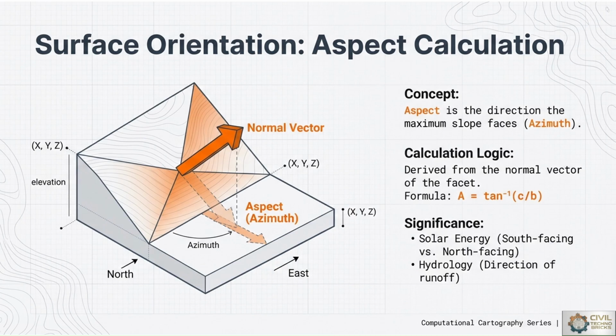For a site engineer designing a building pad, the precision of a TIN is required. A transportation engineer planning a regional corridor might rely on a raster digital elevation model for initial route selection. So the normal vector and aspect are most important for site selection, route planning and route mapping with reference to that aspect calculation.